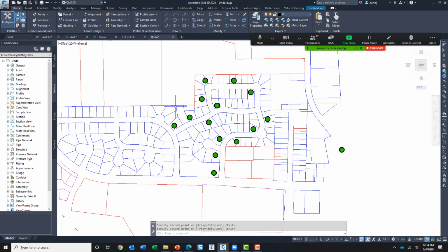It's like, okay, we'll continue to lay some of this out. Not sure how that's going to work. Maybe we'll go through and make some changes to some of the geometry with the lots. Maybe I'll come through and erase, lose some other entities down here on the end. But as I've done my experimentation, I've reached a point where, you know what, I'm not liking the way that's going. I'd like to go back to the point where I was before. So I'm going to type in the command undo, and then I'm going to use the option B for back. So if I select that, it will roll me back in time, undo all of the effects of the commands that I've done, back to that point where I've captured it.